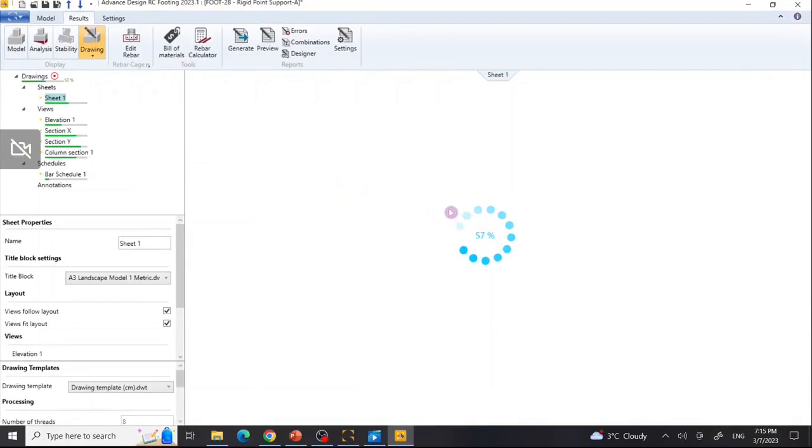The same principles that apply to all the other interactive drawings generated from different modules apply for the footings as well. Any modification on the reinforcement of the footing can generate the drawing again without touching the information. We can modify any parameters on the reinforcement, on the spacing between the links, for example, or the diameter of bars, and this will be applied directly on the drawing.